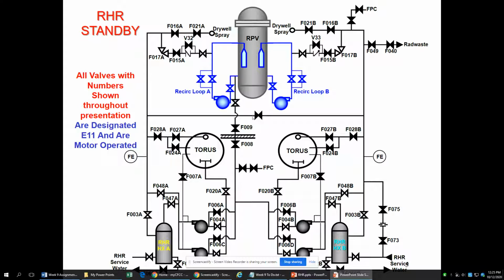There's different places I can get my suction as well. I can take water right here from the reactor. I can take water from the torus, and over here's my discharge to rad waste. Over here's a discharge to fuel pool cooling, and right here is an intake from fuel pool cooling. So the fuel pool is just where we're keeping all that old fuel. Right after an outage, that water is very warm because of all the fuel we just pulled out that's been in there for 6 years. So we might need some extra fuel pool cooling.